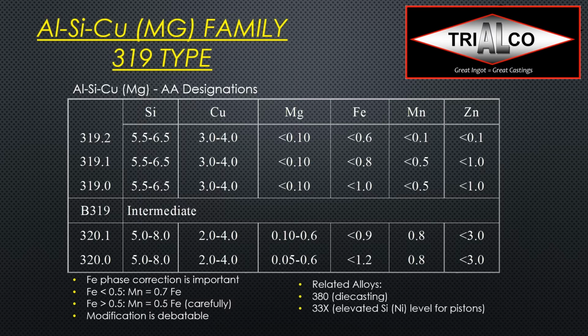Related alloys are, of course, the workhorse of the die casting industry, the 380 type alloys, A380, and then piston alloys like the 330 series with elevated silicon and nickel.